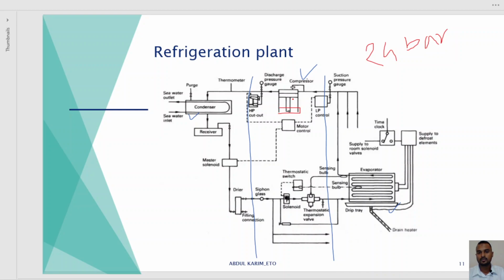And according to the refrigerant plant, that will be the single stage or multi stage. Okay, when the compressor comes to the condenser, we condense this high pressure, high temperature refrigerant by the seawater. But in the system we do not take suction of the seawater from the sea chest directly, because we cannot use the seawater directly.